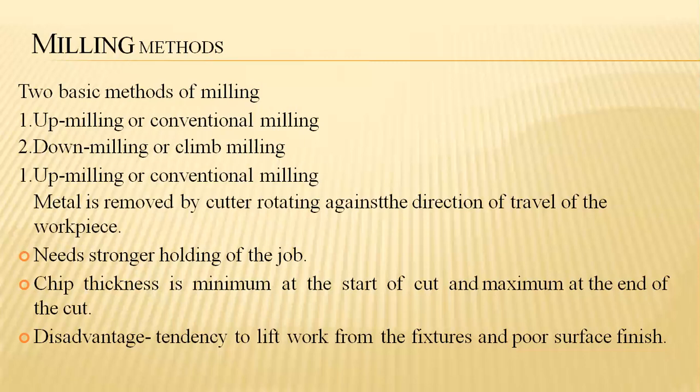And in this type of operation, we get the chip thickness extremely small, that too at the initial state of the cutting process. And at the ending section, we get the maximum range of chip thickness in this milling method.